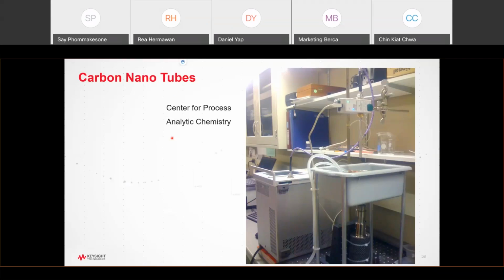With that, note here we use the electronic calibration module. What this electronic calibration module does is when you do the calibration, these connect into part of your setup. You do open, short, you do calibration here using open, short, and water, or any type of standard that you have. And then you submerge this into your material and then continue testing, you know, days, weeks, or whatever.